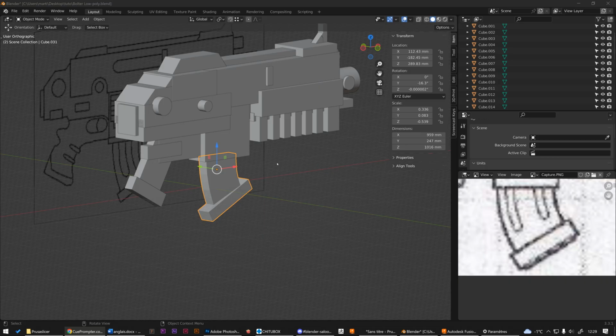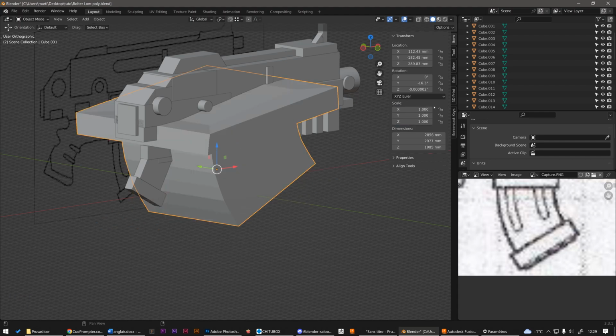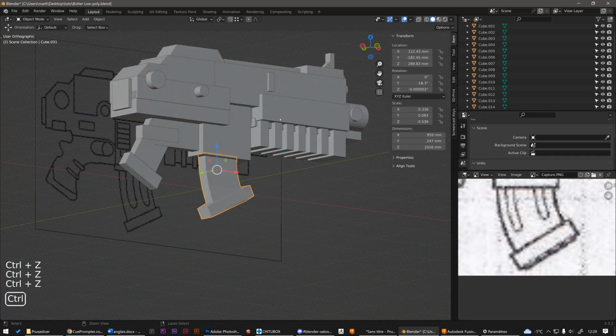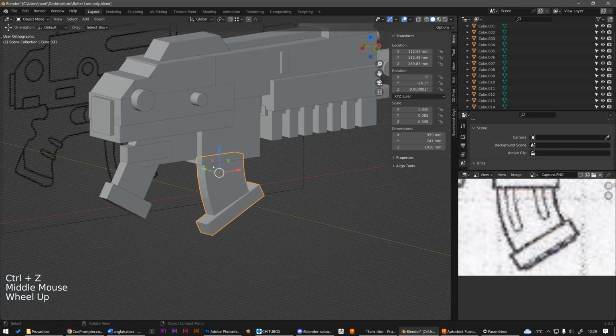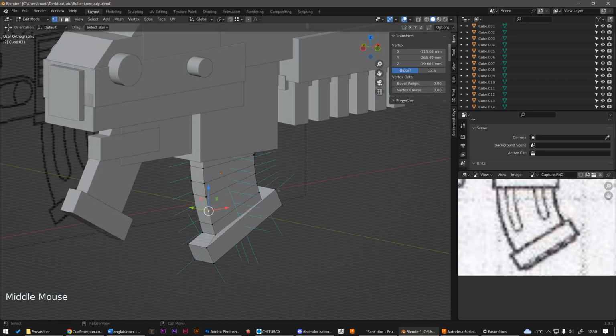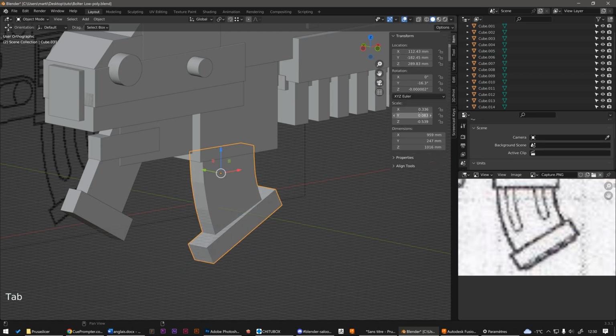How to do that? If we set all the scale values to 1 like that, obviously the object will return to its original scale, and that's not what we intend to do at all. What needs to be done is to recalculate a new position value for each point of the geometry. So these new positions will no longer be the result of a deformation, but absolute positions, without the influence of a scale, whose values can therefore be equal to 1 for all axes again. This operation is called applying a transformation. And fortunately, there is a tool that does all this very complex maths automatically.